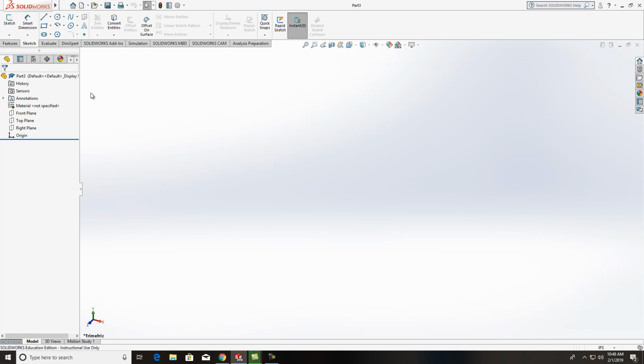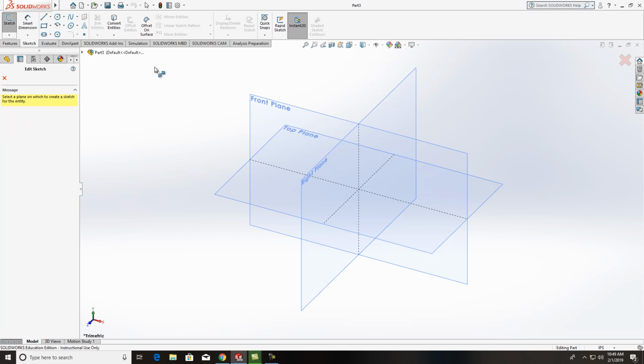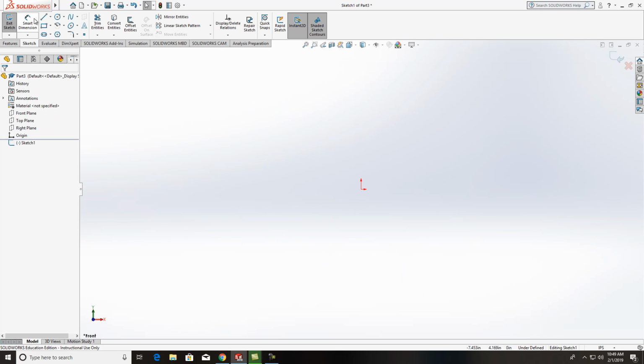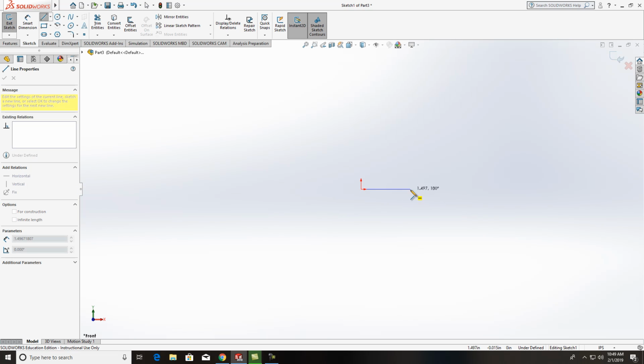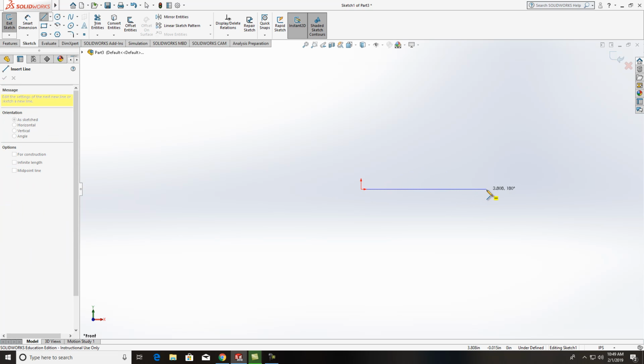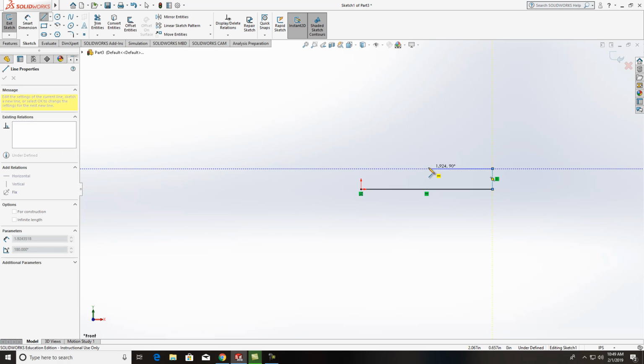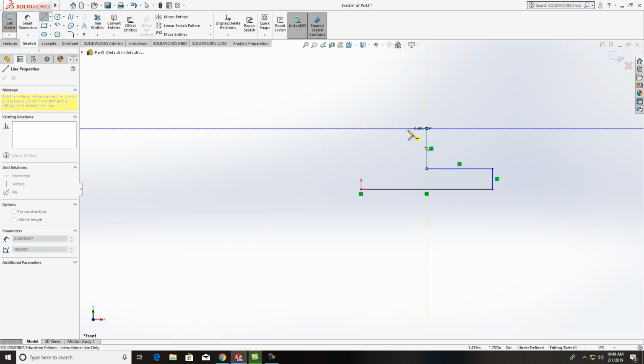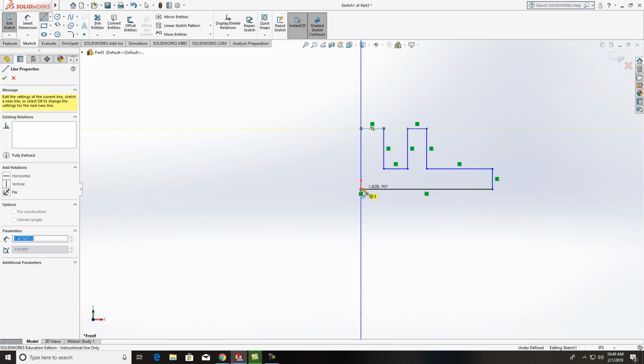It starts in chapter 4. This is basically the saddle bracket design. So I want to draw this thing up, and I'll just start a sketch. And I want to hit line, and I'll just start right there, and I want to bring this line out 3.25. And see, this one doesn't do that, and that's fine. So what you do is just eyeball it close, kind of get it proportional as close as possible, and bring all this stuff in there. And then we'll just use our dimensions to parametrically put this thing together.